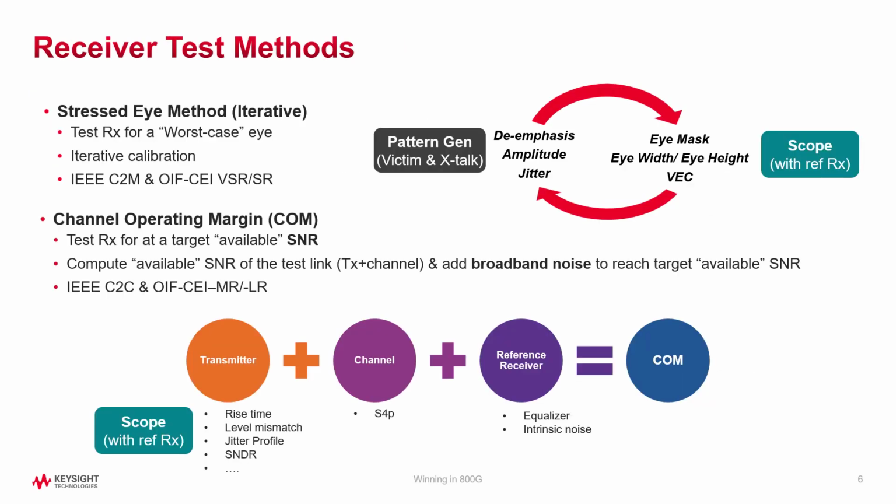So why do we require to perform the receiver testing? In fact, the purpose of receiver testing is to ensure that the chips that you are developing or inserting into your system will work with any compliant transmitters on the other side. This is very crucial, especially for the system integrators, to ensure the interoperability of the receiver by testing against the worst possible combination of compliant transmitter and compliant channel. In another word, we take into the consideration of worst possible eyes that could be measured on the receiver side.